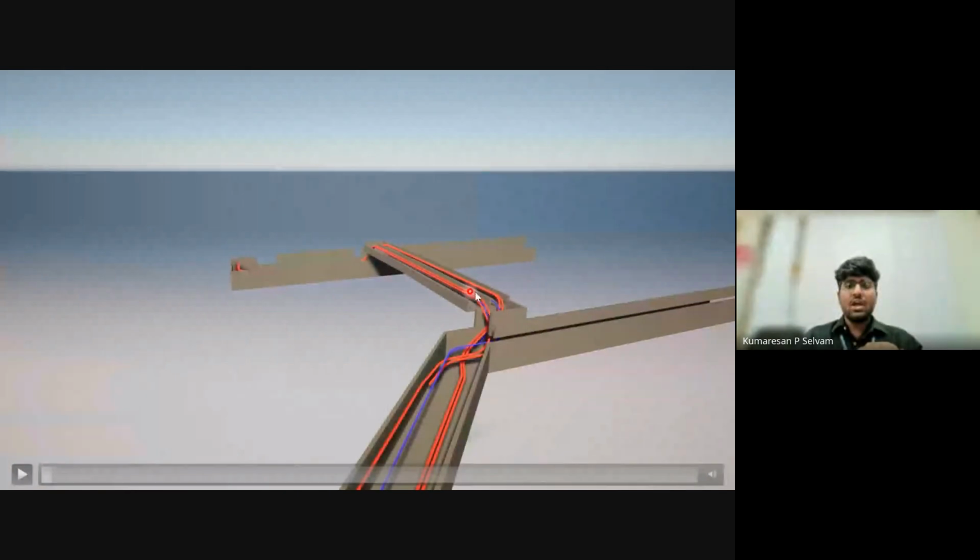that should be followed. But in the 2D drawings, that minimum bending radius was not considered, and all the drawings were submitted and the client approved, then the site people found out that there is a problem in the bending radius, and you cannot bend the cable and take it through. Then we took it into a BIM model, and we developed a model where it will automatically calculate the bending radius, and based on that it will model the ducts, at what height they should be located and everything. This process was completely automated.